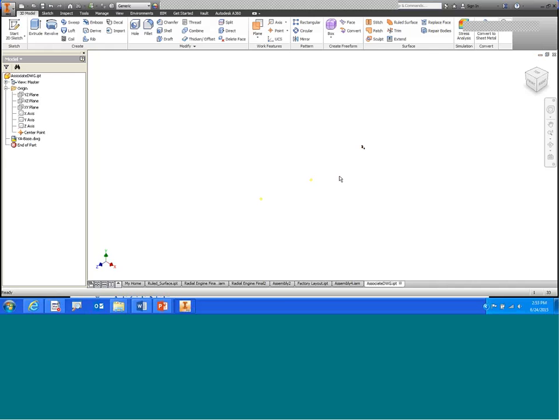So what's happening is the import of that DWG file isn't aligning with the actual center point of the model because of where the center point was on the actual drawing. Sometimes I find it comes in beautifully, in the way that the drawing file was created, it positions it right, but you also need to know how to use these translation tools to relocate it.